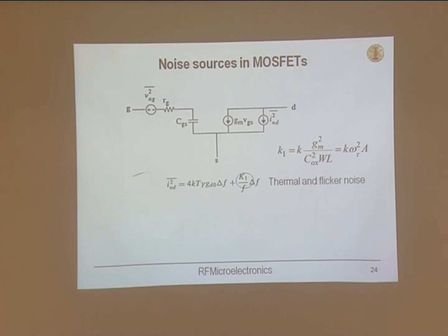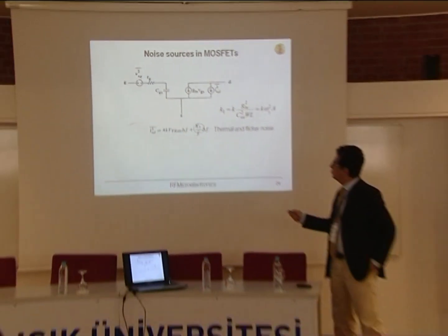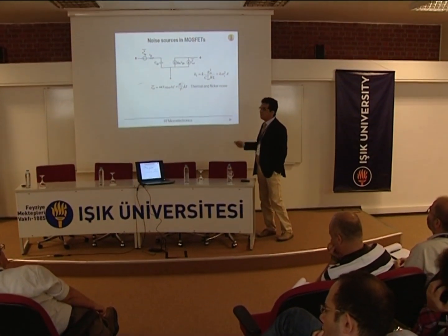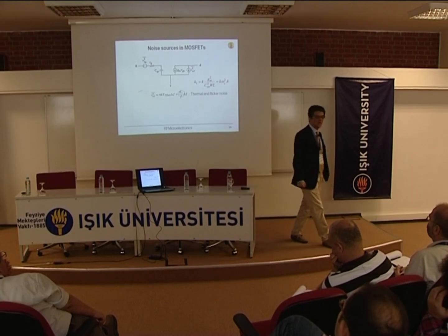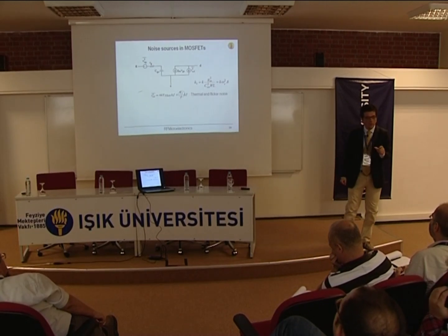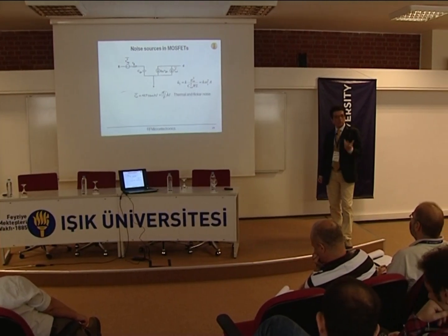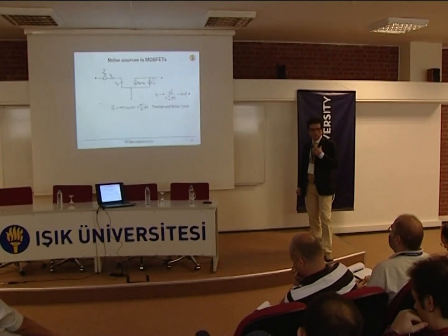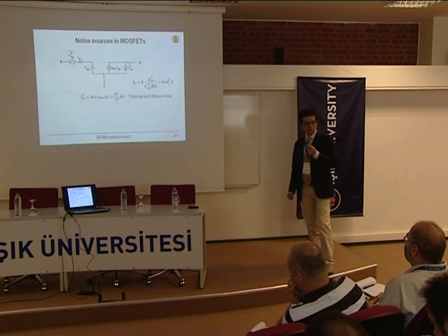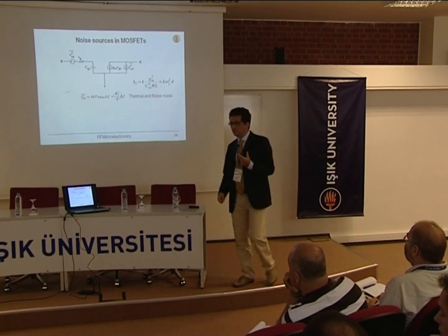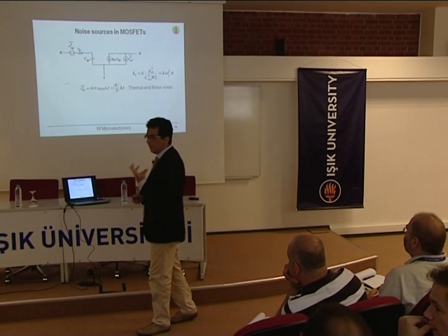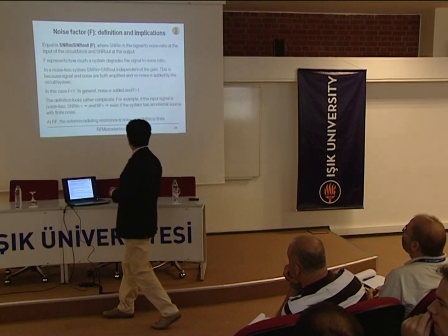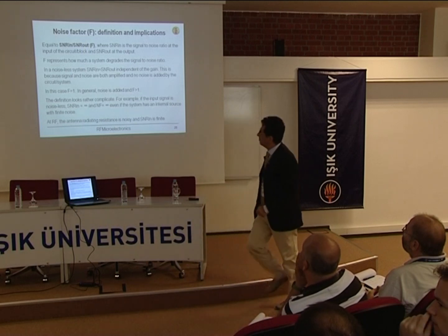low noise amplifiers and mixers. Then you can also have, and I added here, a resistive component that in a MOS device can be associated, for example, to a real resistive term, the polysilicon and whatever. In a bipolar device, it's more fundamental, more related to the physics of the device, whereas in a MOS, it's only the parasitic of the gate access. Now, and then maybe we can break.